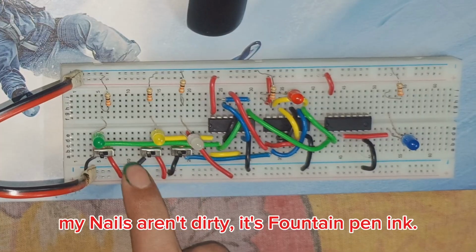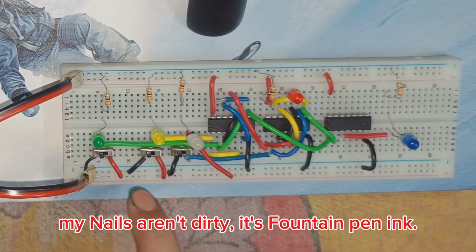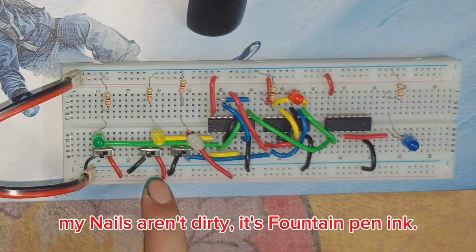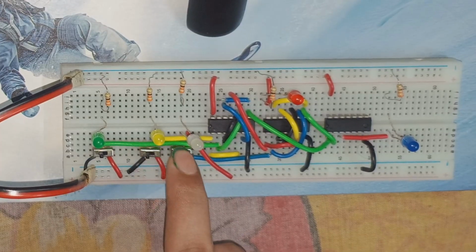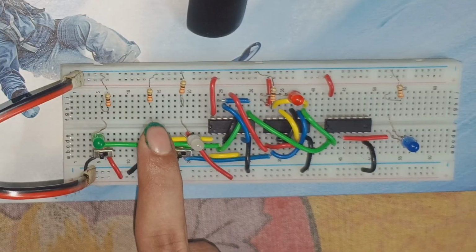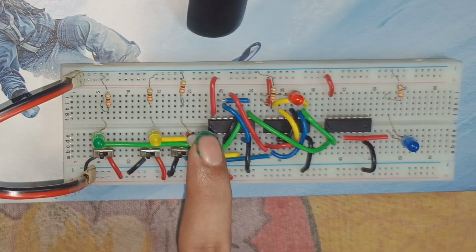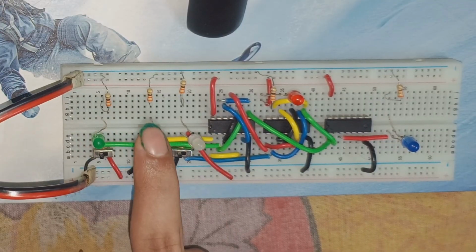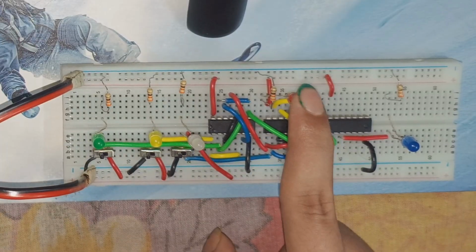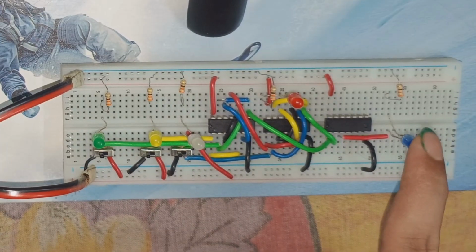The left side is connected to black wire to the ground, and right sides are connected to the red wire to the VCC or 5 volt supply. So all the switches are on the left side, so all the input should be 0. This is the first input, this is the second input, and this is the borrow in. So we can say that this is A, this is B, this is borrow in, this is the difference here, and this is the borrow out.